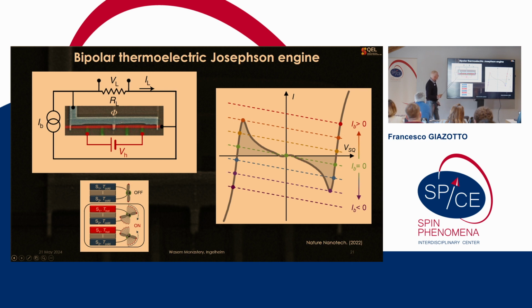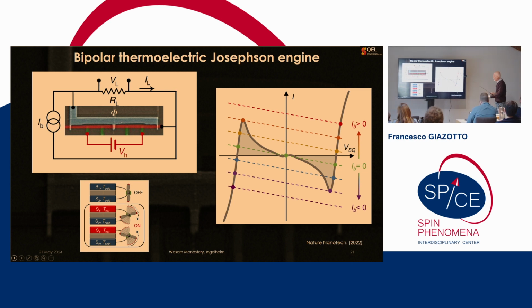So the idea is the following. We create this nonlinear thermoelectric effect, and in suitable conditions, a current will start to flow. So the current will be the biasing current in parallel with the current flowing in the load itself. If we measure the voltage drop VL, the power developed in the system on this load will be just VL squared over RL. So there is a straightforward way to measure the power that our Josephson junction can deliver to our load.